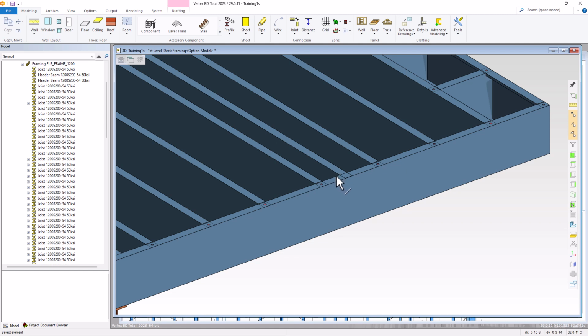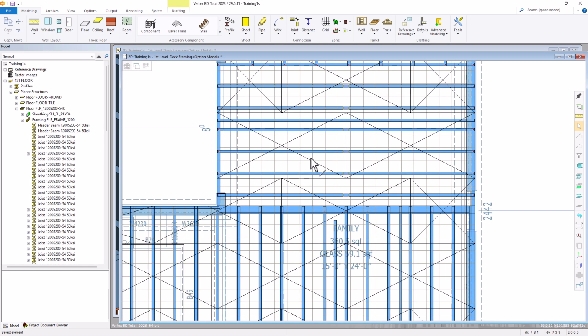Using the fourth option under Add Profile can require more work when aligning the profile to the floor plane. This option can apply a profile to any plane in the structure, which requires more adjustments in order to line up the profile to the plane. Hit the F2 key to go back to 2D, and Shift A to zoom out.